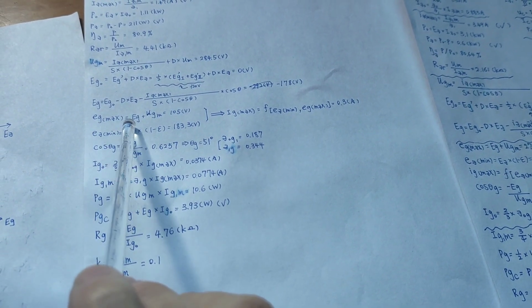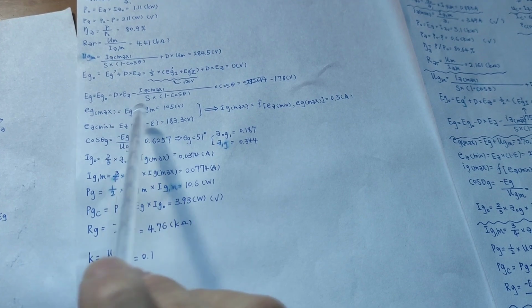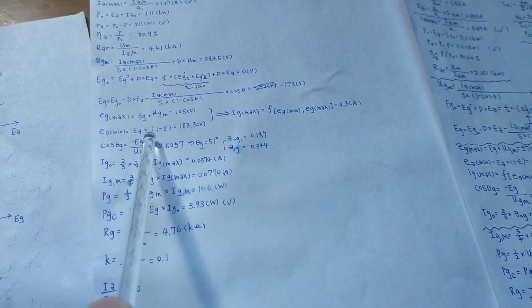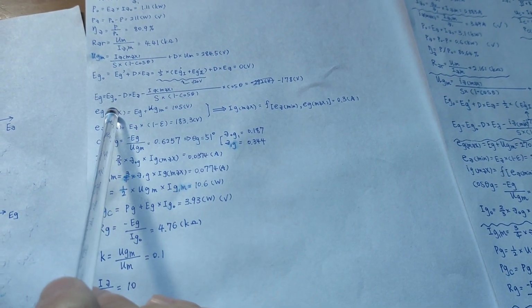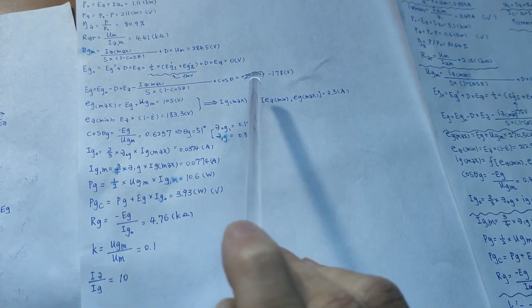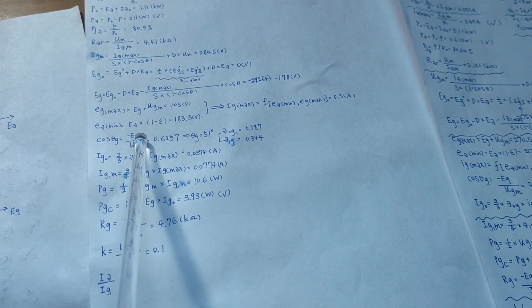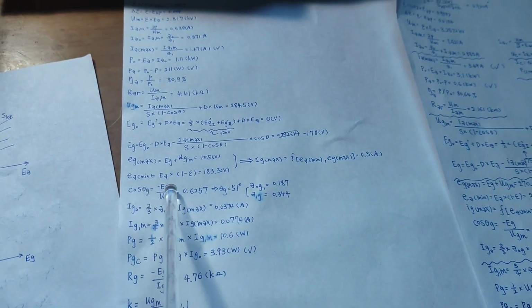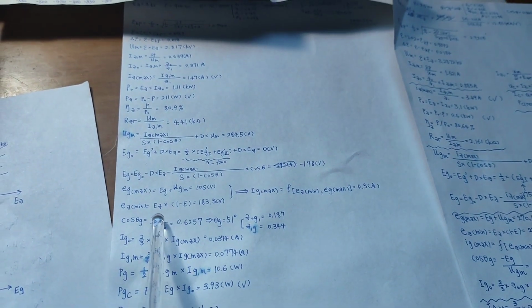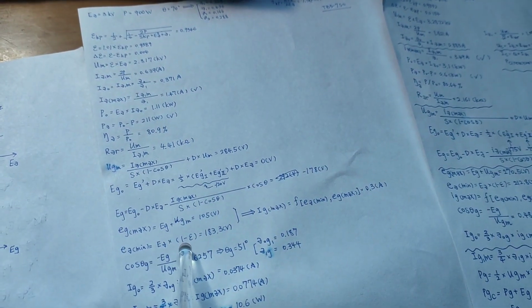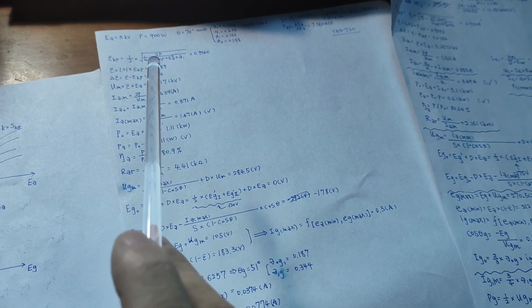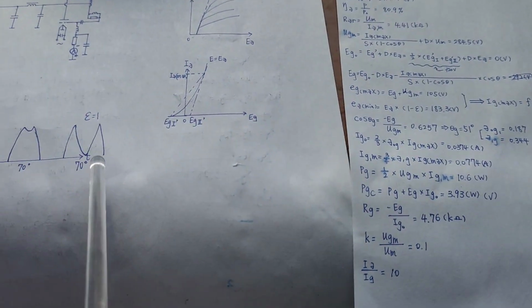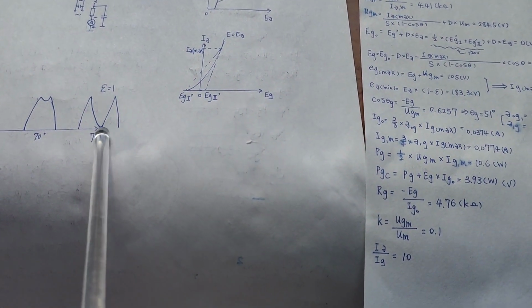And the maximum gate voltage, I guess you already know how to do that. Just this static situation plus the maximum voltage, then you will get the maximum gate voltage. The minimum voltage you can just do, sorry, that is not the gate, the anode. So to get that, you can simply, by using this equation, the anode input voltage times 1 minus the factor you just calculated, right? So this voltage actually means how high this point will be above the ground.